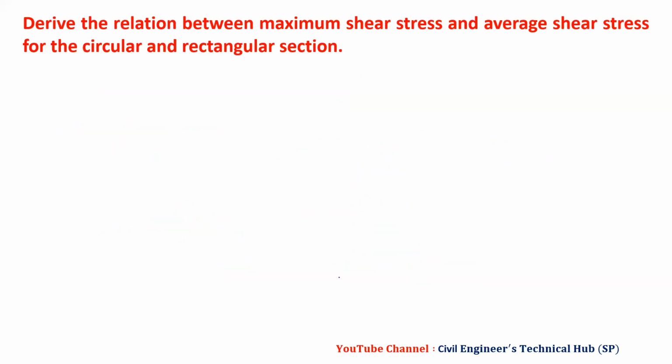And then third part we have derive the relation between maximum shear stress and average shear stress for the circular and rectangular section. Now for circular section. So now we have V, tau average shear stress. Tau average equal to V upon A. So V we have and area will be pi by 4 into D square.